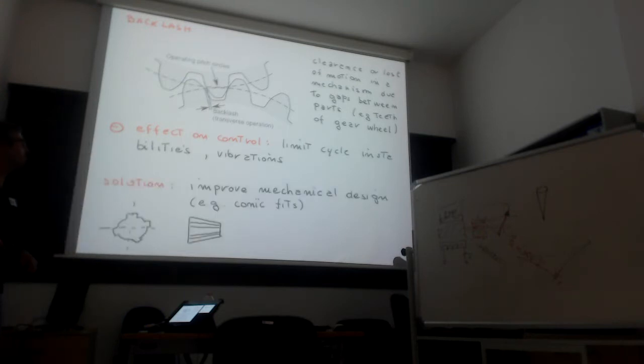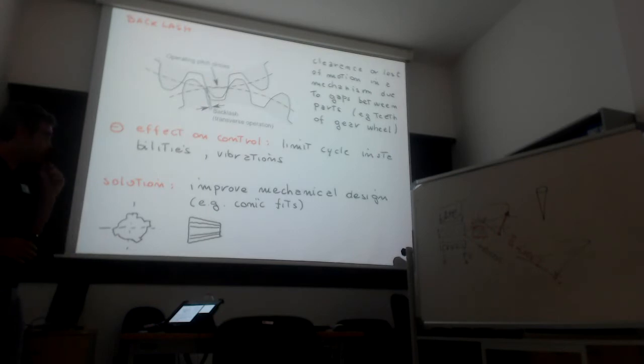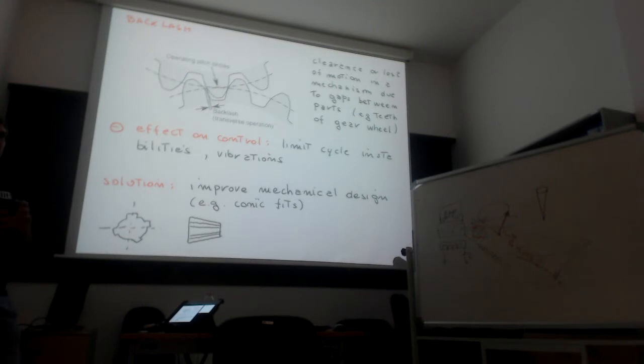The only way to deal with this, I'm sorry, is doing a good mechanical design, so trying to use conic fits, spirals that enable you to reduce the backlash.